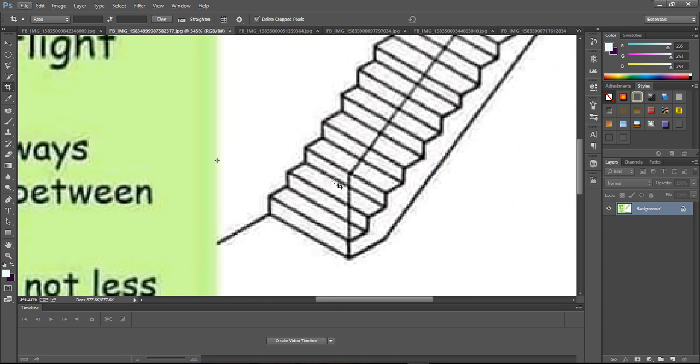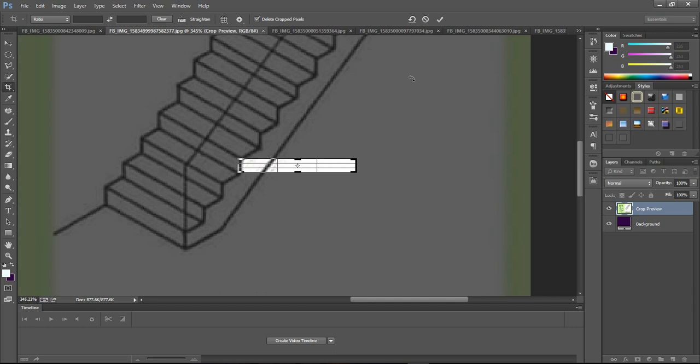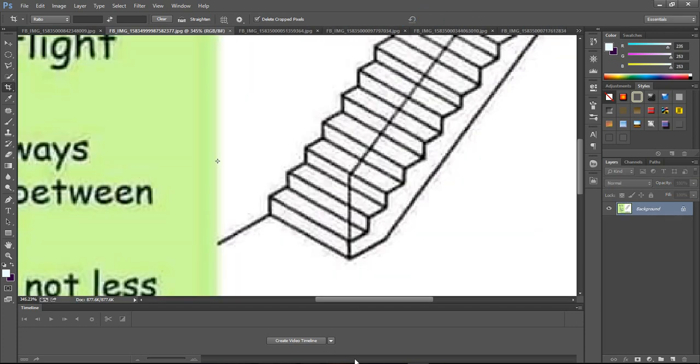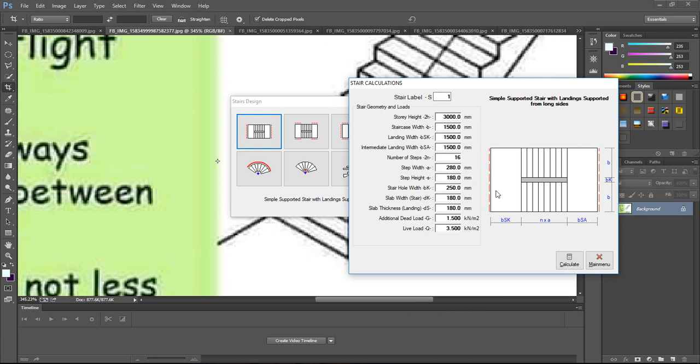This is a riser. From the ground up is a riser. From another ground up is a riser. So riser is this very unit here. I don't know if you really understand what I mean. That's a riser. In here, our riser is supposed to be 150. That's what I like using. That's step height. Our riser, I love using it 150.